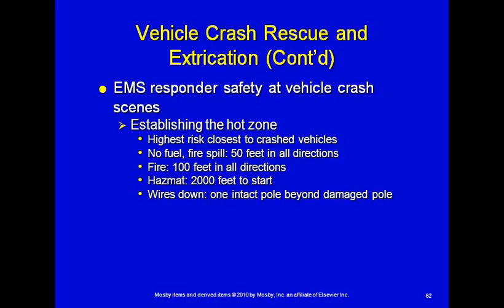You may have to establish a hot zone. Hot zone is the highest risk closest to the crash vehicles. If there's fuel that's spilled, there's a potential for fire. You should be 50 feet evacuated in all directions from the hot zone. If fire is a potential, then you should be 100 feet in all directions from the hot zone. And if you're dealing with a hazmat scene, you should be 2,000 feet to start with until you identify your parameters.